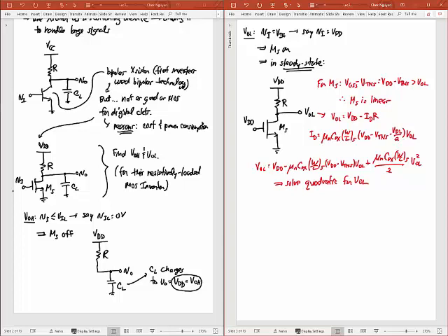And so when I put a big voltage here, what's supposed to happen is my output will go to some low voltage. That means I got a voltage big enough at the gate to keep the transistor on, but the output is such a small voltage that this VDD minus VTN is going to be greater than that voltage. That means the VGS minus VT is greater than the VDS, which means this transistor is in the linear region.